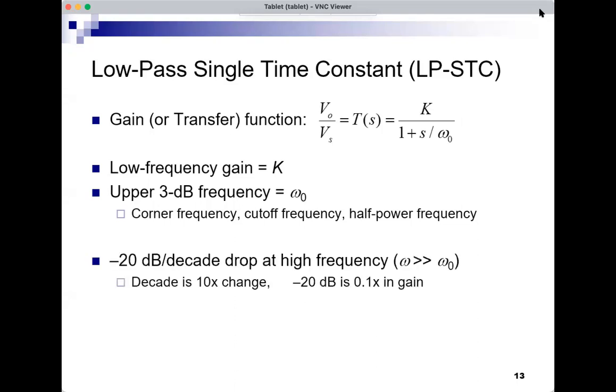All right. So what happens at omega 0, after omega 0? Here's what happens. When the frequency exceeds omega 0, in this example, it's 1 million radians per second. So when I know what it is, here's what I can say. That if the frequency at the input exceeds omega 0 and becomes larger, maybe much larger, quite larger than omega 0, then the gain will drop.